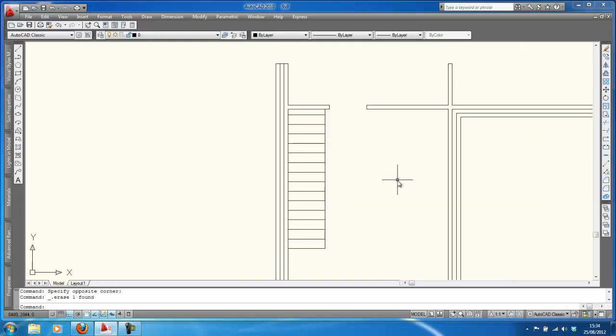I've deleted it. Now, in a normal house, you will find anything between 13 to 14 risers, and we've got 1, 2, 3, 4, 5, 6, 7, 8, 9, 10, 11, 12, 13, 14, and let's say this is looking exactly now at the first floor. Well, what happens is that on the plan we normally show part of the stair. So let's say at this point or at this point, I will take this and move it like that.